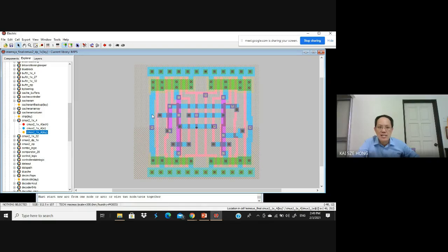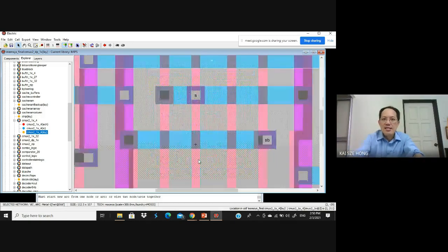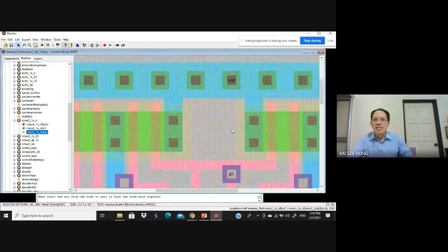So the blue color one is actually also a metal. Yeah. So here, and then we have the metal one. Metal one is the first layer metal, and then we have this one. Transistor is basically the whole section over here and here. We have the NMOS and PMOS design for this. So yeah, you can see inside actually we have all these transistors over here.